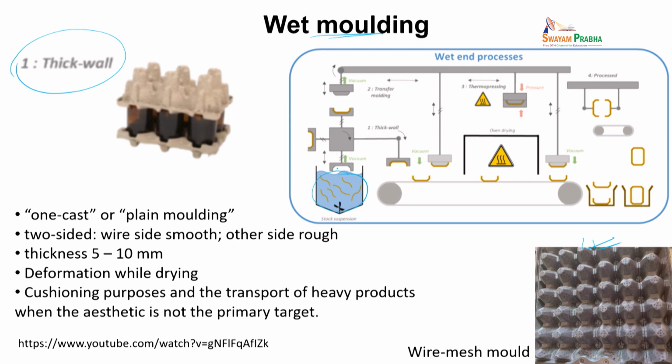Okay, so you can see that there is a plunger that comes that will have this mold, and then you apply vacuum to pull, you suck vacuum. Then what will happen is this fiber will start getting attached to the inner wall of this. When you apply vacuum, once you apply enough vacuum, you will see a thin layer of cellulose coming on the top. So you'll have this kind of a situation. Then you can release the vacuum, and this product will drop down onto a conveyor belt.